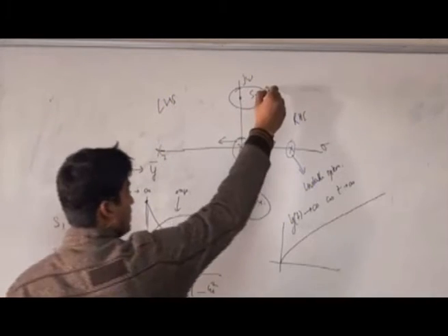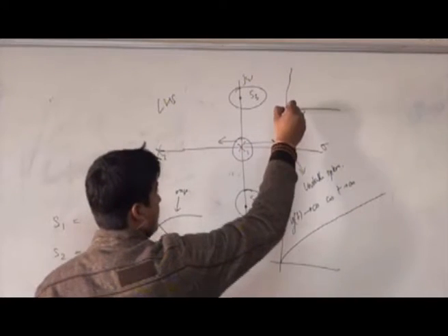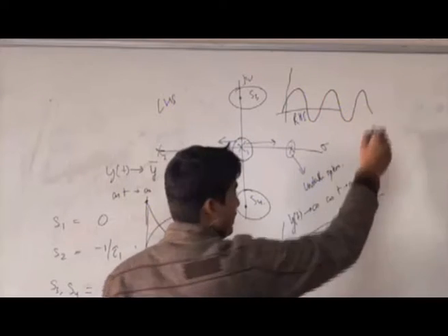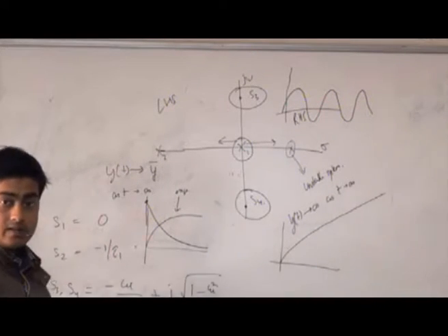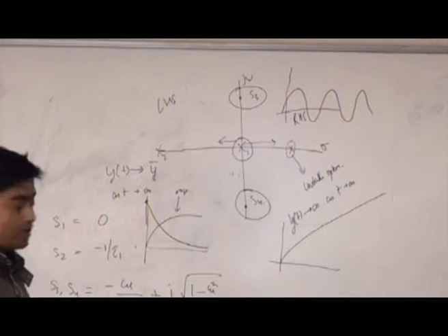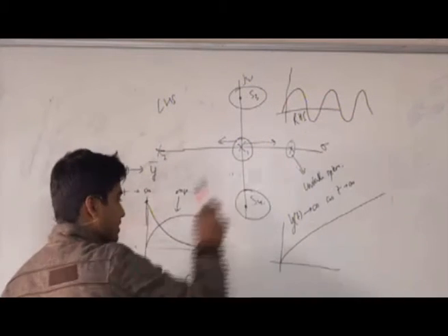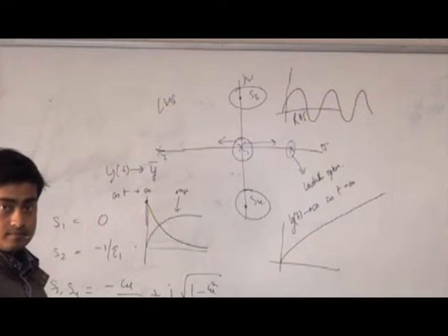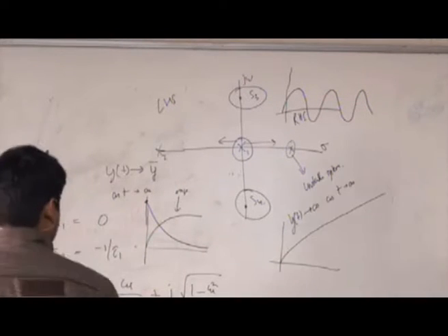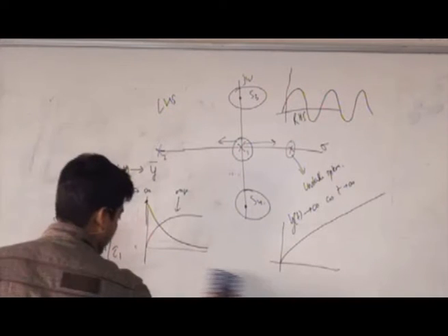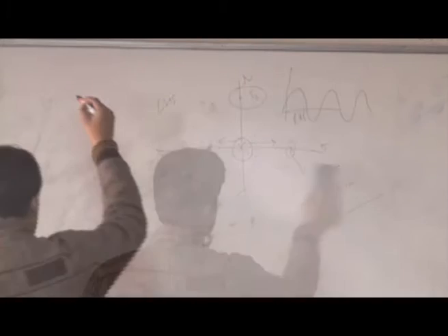For these poles on the imaginary axis, I will have some oscillatory behavior, and if they are mixed with the real poles, it will have a damping effect. It will have first of all the oscillatory behavior plus the decaying behavior. Now coming on to the lead lag system, what we will do now is consider the first order system and then add a zero to it.